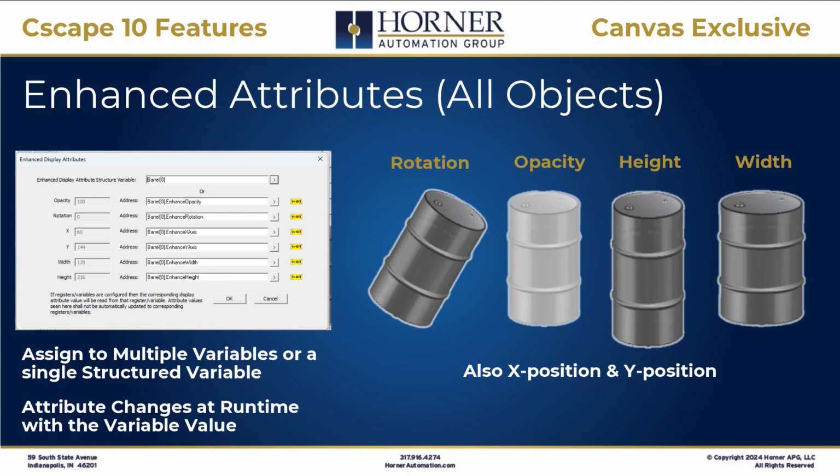With Canvas and Cscape 10, you now also have enhanced attributes. Enhanced attributes can be modified at runtime, and those are things like the X position on the screen of an object, the Y position, the rotation of an object, its opacity, not just visible or invisible, but 0 to 100% opacity. The height can be changed, and the width can be changed. So all those can be changed at runtime.